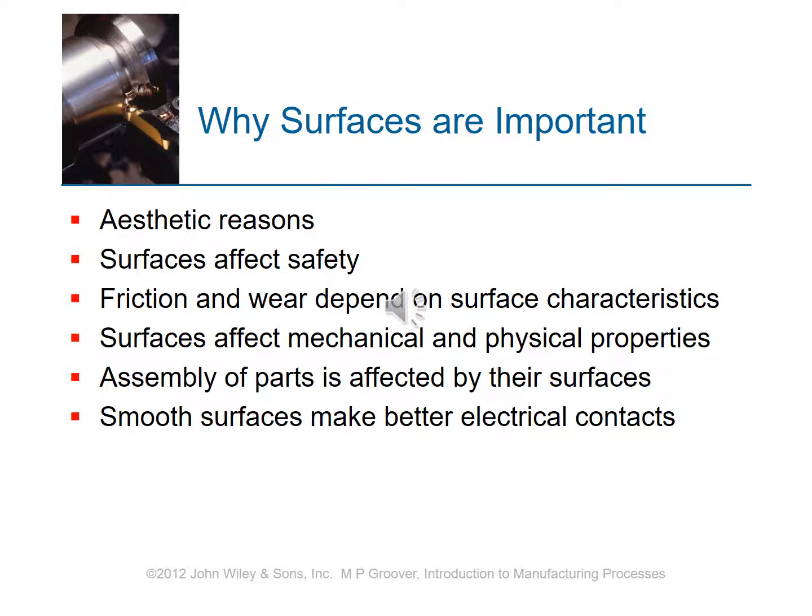So why are they important? Well, they've got to look pretty, aesthetic reasons. Surfaces affect safety. We've all slipped in the bathtub, right? As you use these things, friction and wear will depend on the surface characteristics, the mechanical and physical properties. We saw how sticky spools were in hydraulics. If we smoothed out the surface, made it less rough, it usually went away. And assembly, I mean, we've all tried to stick a bolt through a hole and had a burr or something keep us from doing it.